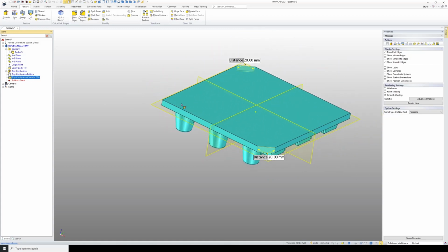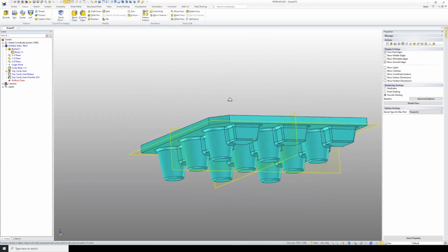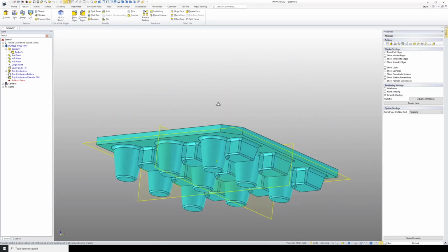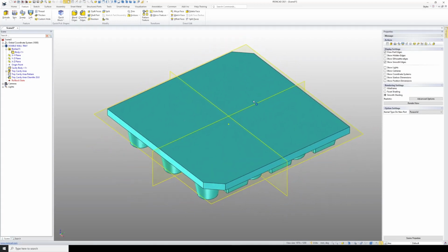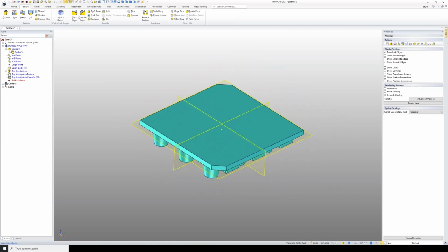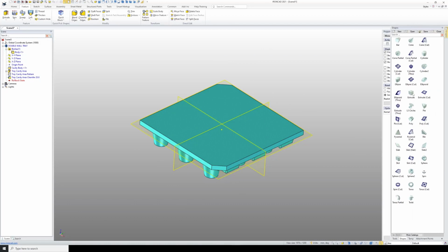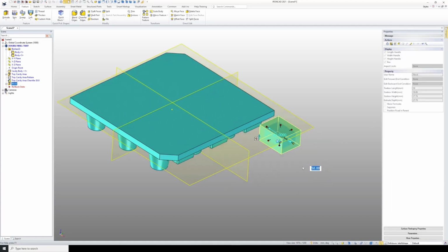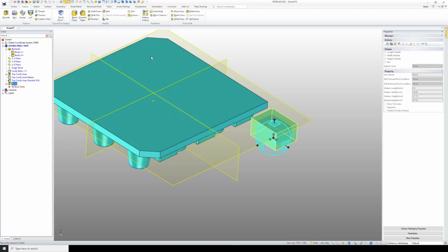And now I'm going to extrude a different body. So this is the body that we're going to use for subtracting from the body of our tray. So we need to actually add now a body to our part that's going to represent the tray body itself. So we'll use our extrude Intellishape again, and again I'm just going to drop it into the scene here, and I'm going to apply it to the origin,